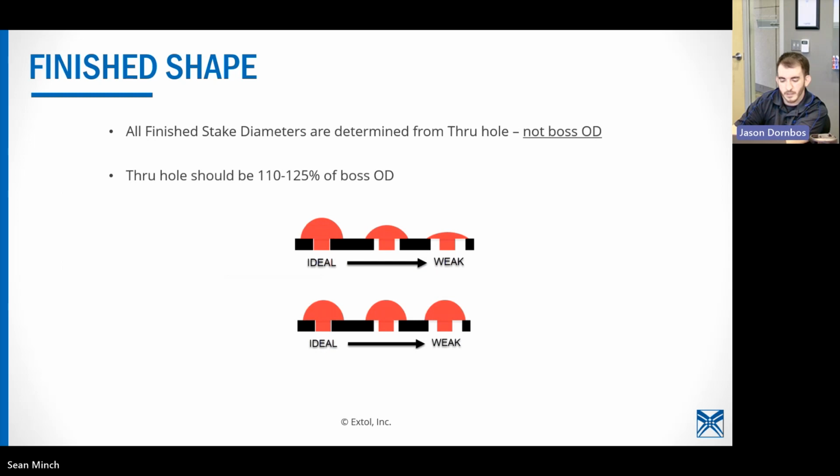So here we have a couple of graphics. The nanoSTAKE tip can have a special coating. We have done special coatings for glass-filled material projects, where we can apply a coating to help improve the longevity, because as you can imagine, glass inside of plastic will maybe deteriorate the tool over time. So that's really what we offer for that technology, but not on every one. That's not a standard practice, if you will.